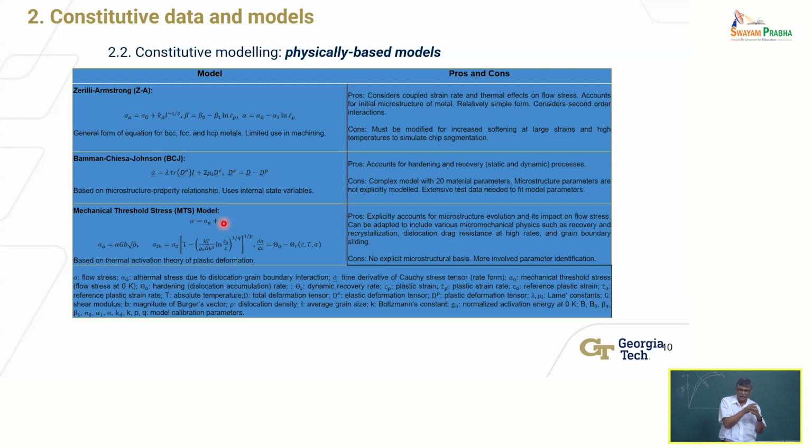You can simulate dislocation generation and so on, and then combine what's happening at that small atomistic scale with something at the mesoscale, right? Which would be something like a crystal plasticity model, all the way to a continuum scale.